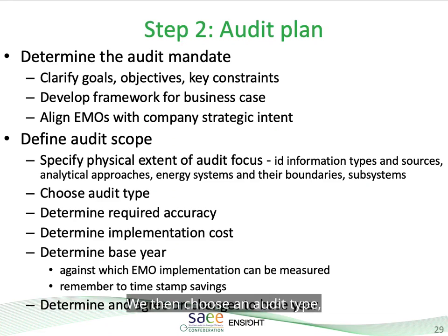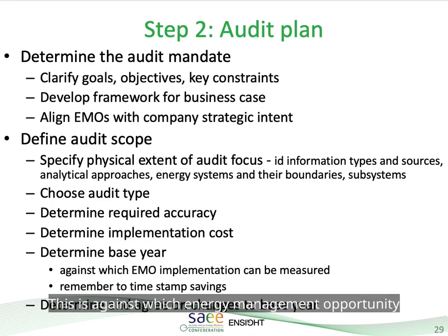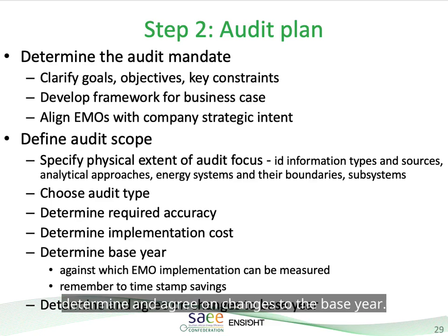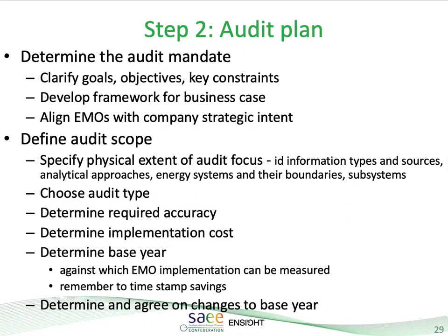We then choose an audit type, determine the required accuracy, determine the implementation costs, and determine the base year. This is against which energy management opportunity implementation can be measured. Remember to timestamp savings. Determine and agree on changes to the base year.